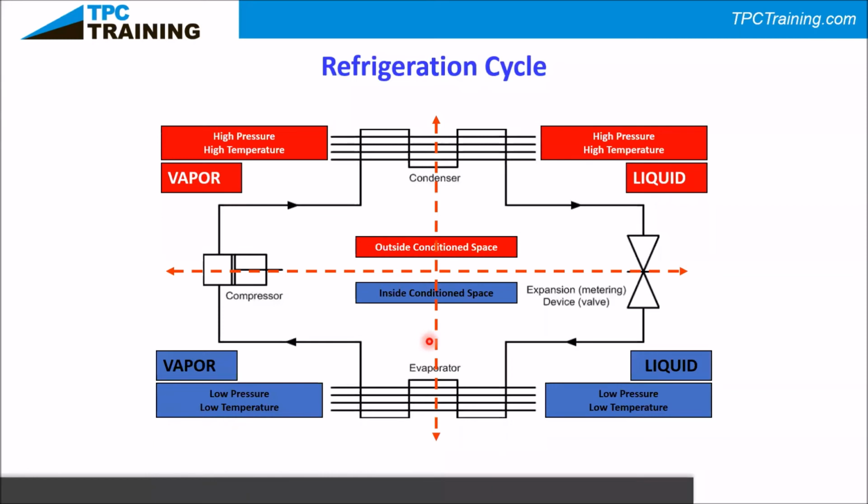They're better for warmer climates because once the outside air temperature falls so low, the evaporator, now outside, has to have a refrigerant temperature so much colder than the air that it's going to cause freezing on the coil.